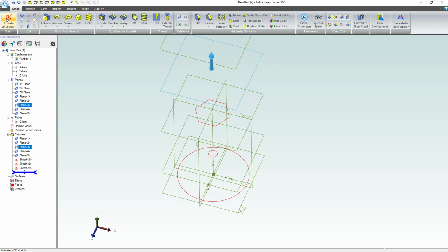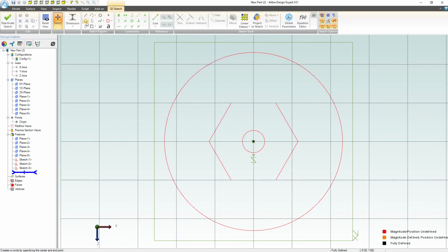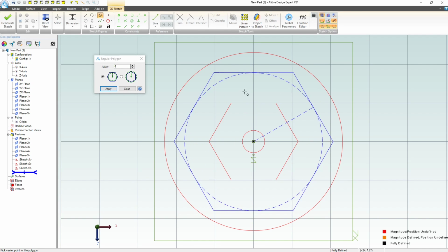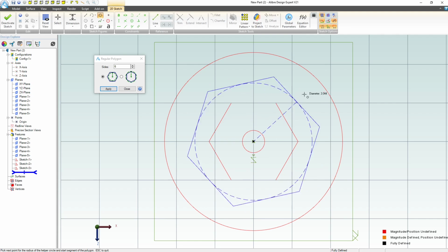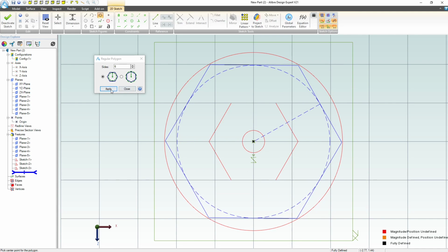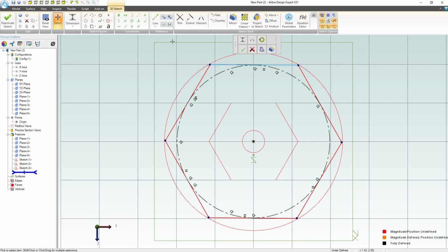Let's do the same thing. 2D sketch here. Let's choose a hexagonal cross-section. Now I'd like to twist this as it goes up, but for my initial loft, sometimes things work a little more smoothly to loft it straight first, and that may help create consistency throughout the loft and just make sure that it looks good straight.